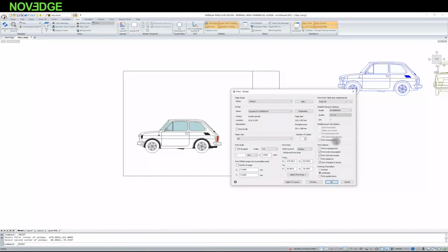What is it used for? Well, for example, when you have a map and you draw the area you want to color, you have to have them in one shade. It won't be a regular hatch, but a solid hatch, that is the entire surface, but you may want this map underneath to be visible because there is something on it. Then, for example, in hatching, you define transparency.